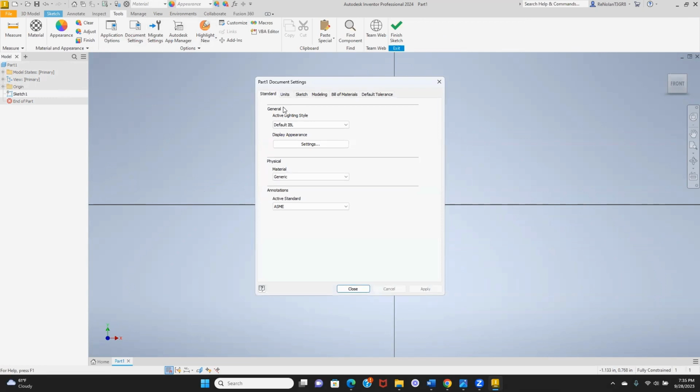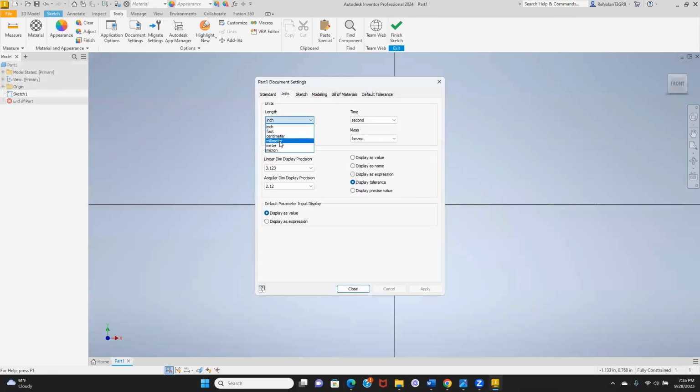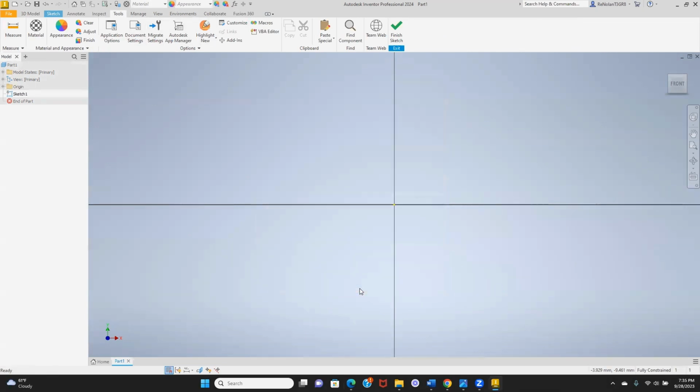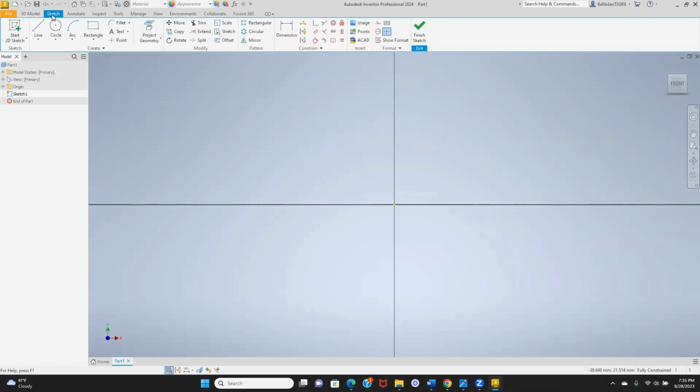First, let's make sure our units are set right. Get into millimeters now. Let's get back to our sketch environment and our arc. We're going to use our center point as the point of interest of our arc, or the center point of our arc. And we're going to use the two endpoints of that being along the negative y-axis and along the positive x-axis.